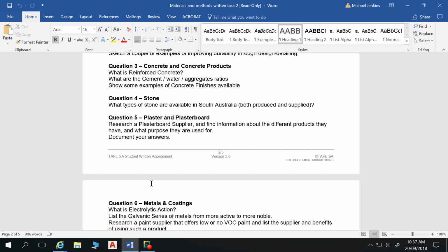Yeah, look, that is a question for the engineer. I would expect it's going to be the same stuff. Yeah. It's just one of those little mental notes I've got. So in that scenario, I don't see that it needs to be super workable. Certainly you've got to do it in lifts, so you don't go blasting out. Oh, actually, core fill, yeah. Actually, I'd have to say it would blast those bits apart, because you've got two separate leaves of masonry happening.